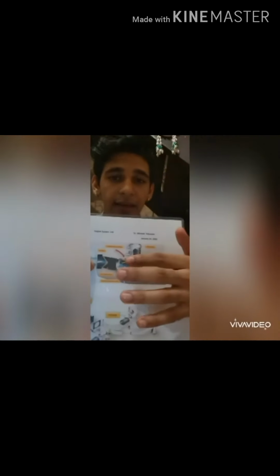So this one is an example of a non-supercharged induction system using a carburetor. The components are the carburetor air valve, air filter, air intake duct, cold air actuator lever, drain line, temperature valve, and carburetor. As we can see, there are blue and red arrows. The blue one represents cold air, and this one is for hot air.